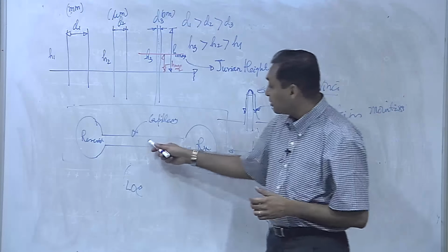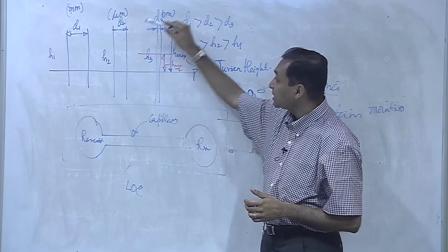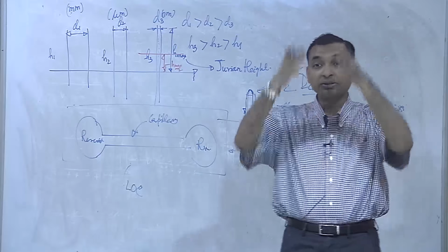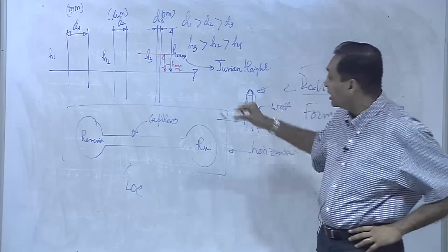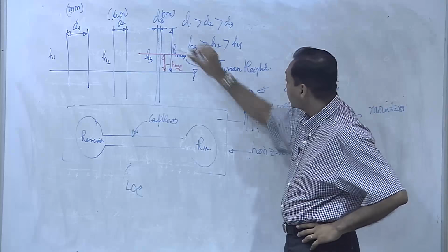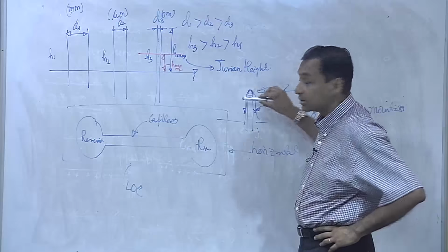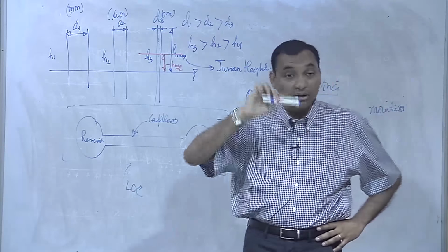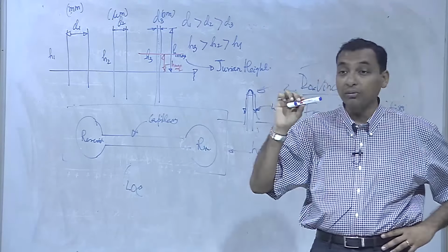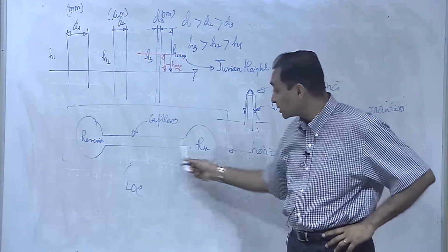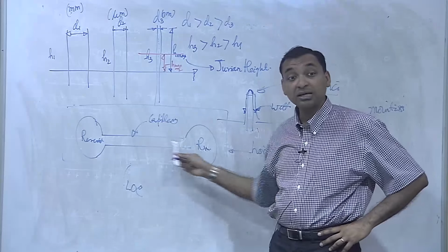When gravity plays a role, gravity tries to pull this down. When it is rising, if you look minutely at these things, even when I cut it to half, there will be some sort of oscillation. That oscillation in the capillary flow is because of gravity, whereas in a horizontal capillary, you will never see any oscillation.